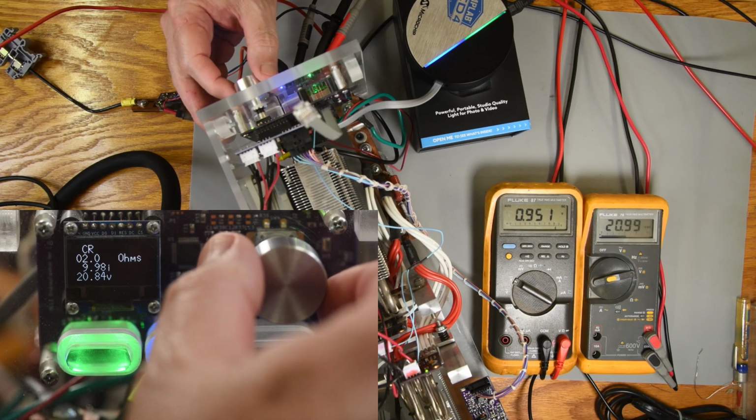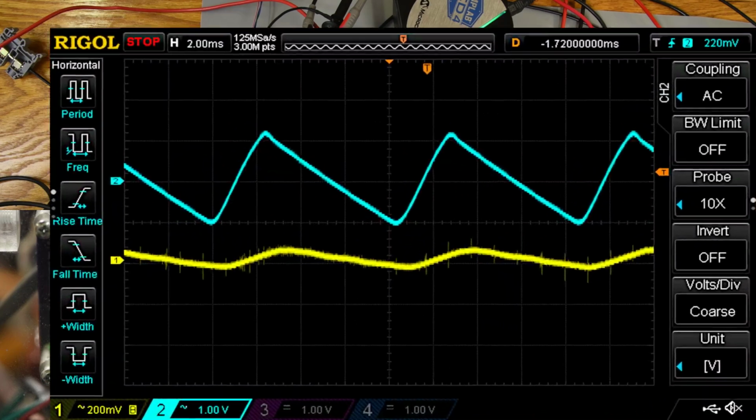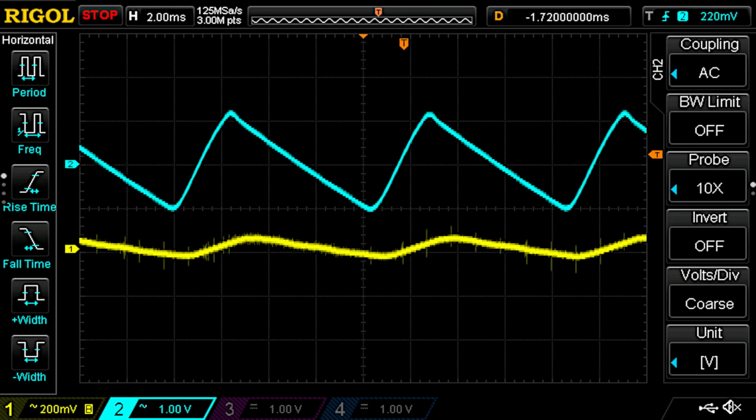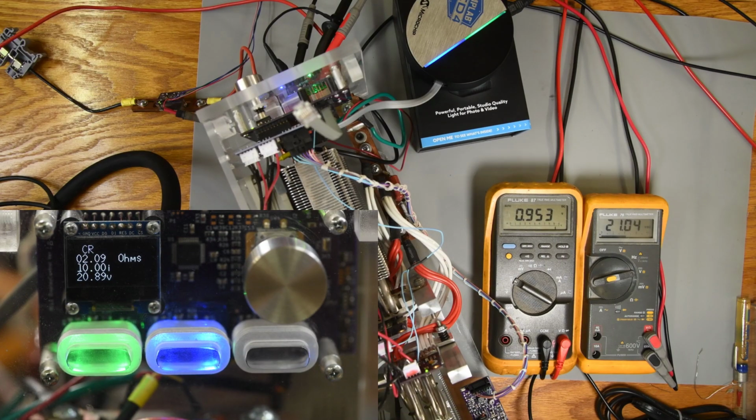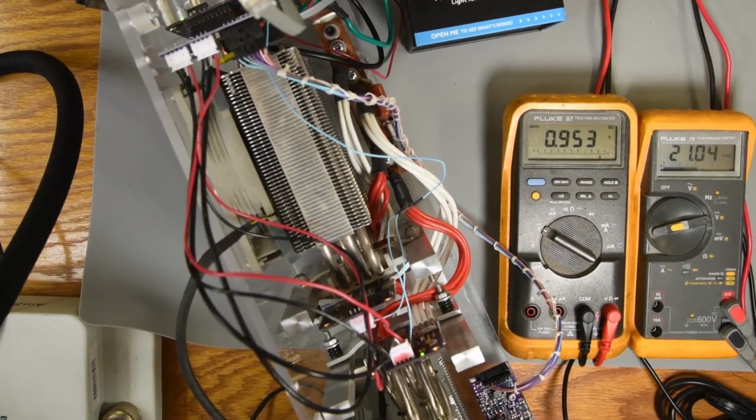And lastly, the constant resistance, set to a little over 2 ohms. That is really what I would expect to see. The current change clamp in the constant resistance code is set very low, less than a half an amp a millisecond. I think that's why the current ramp is kind of flat with rounded edges. Again, I can certainly live with this. Problem is when it gets above 4 ohms or so, it starts to get a bit of current ripple.